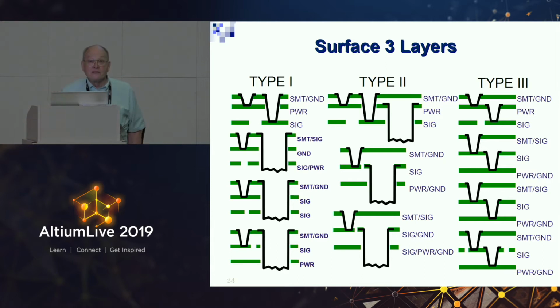Yeah? If you do this, do you then eliminate all traces on the top layers? Because else you would have a ground plane. Right. Well, and so the one thing is, remember how close on the breakout the via was to the SMT land? Well, that, like on the type 2 there, that could be a skip via down to layer 3.